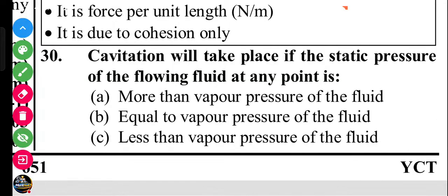Next question. Cavitation will take place if the static pressure of the fluid at any point is A. more than the vapor pressure of the fluid, B. equal to the vapor pressure of the fluid, C. less than the vapor pressure of the fluid. C is the answer, less than the vapor pressure of the fluid. Do you know what cavitation is?